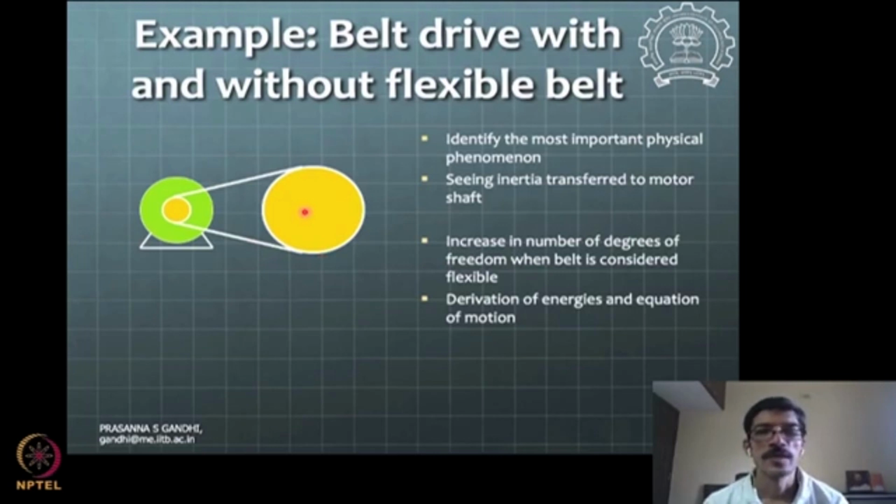We can move on from here now. You carry out this derivation, see what equation of motion you get, and once you get it, interpret it in terms of the Newtonian formulation, looking at whether these are the appropriate terms coming into the final equation. You can do that exercise. This becomes an underactuated system. It has only one actuation, for the motor, but 2 degrees of freedom, the motor and the load. We'll see how these kinds of systems can be dealt with for control.